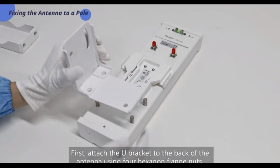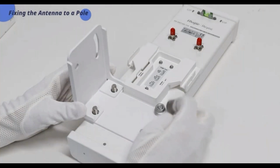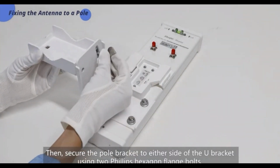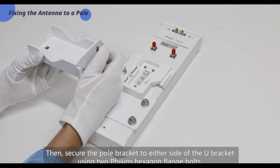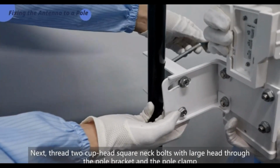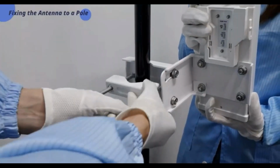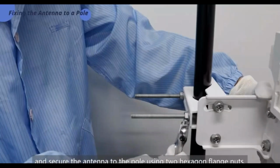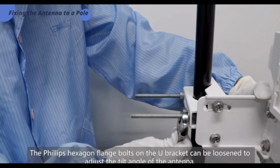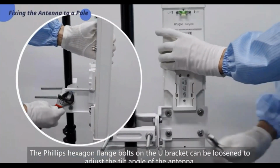First, attach the U-bracket to the back of the antenna using 4 hexagon flange nuts. Then, secure the pole bracket to either side of the U-bracket using 2 Phillips hexagon flange bolts. Next, thread 2 cuphead square neck bolts with large head through the pole bracket and the pole clamp, and secure the antenna to the pole using 2 hexagon flange nuts. The Phillips hexagon flange bolts on the U-bracket can be loosened to adjust the tilt angle of the antenna.